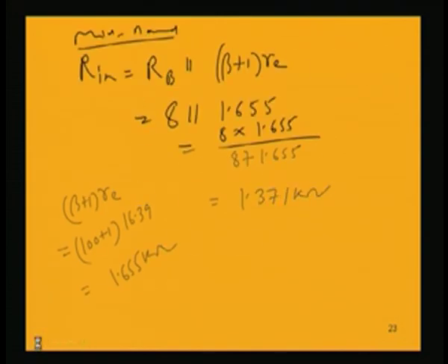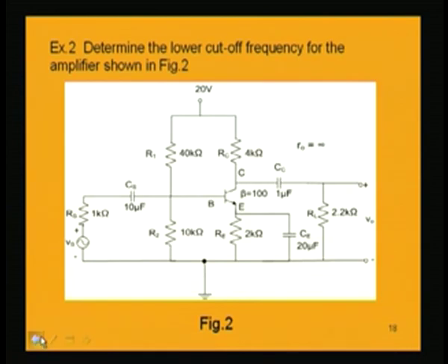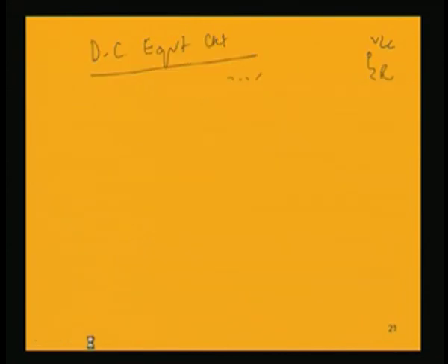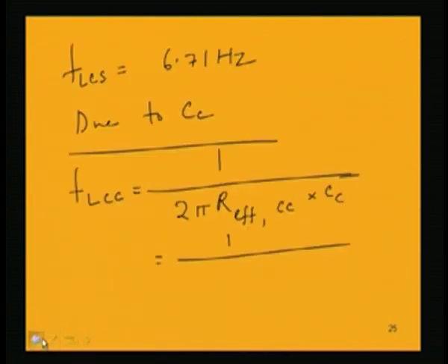In order to find that, let us look into the amplifier circuit from Cc. In this small signal analysis, if we look from Cc, this coupling capacitor, the effective resistance is actually a series resistance between Rc and RL. So, this series resistance is the effective resistance seen by the coupling capacitor, which is Rc plus RL, into Cc.